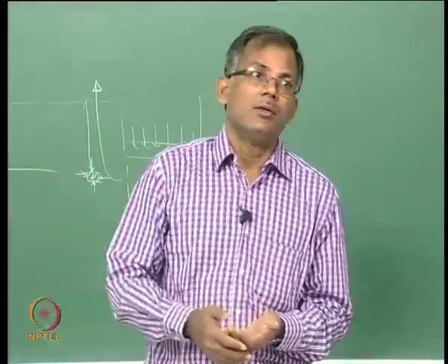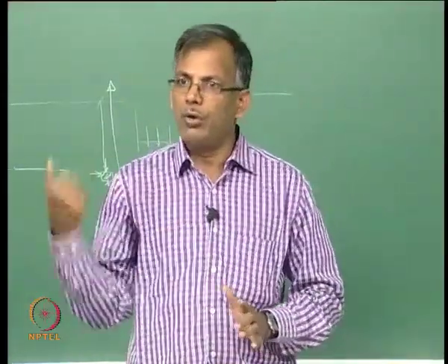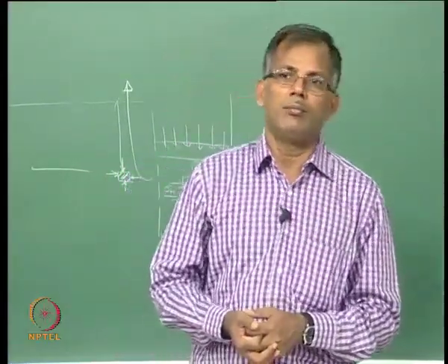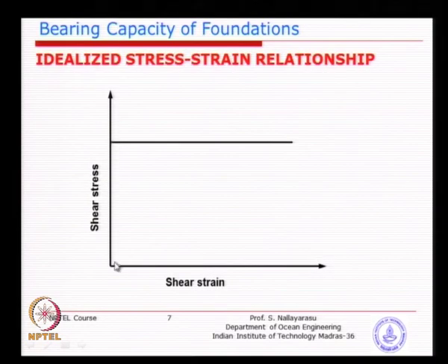Whereas in this case, once you break the bond, or once you make this strain happen on the soil, even if you remove the load afterwards, what will happen? It will never be able to come back, because there is no structural bonding. That is one of the problems. That is why we need to be very careful. When we reach this capacity, it is not good. So, we need to find a factor of safety on the shear stress or shear strain. Basically, somewhere here we should stop, so that it does not permanently break, and that is the easiest way of adapting to foundation failure.